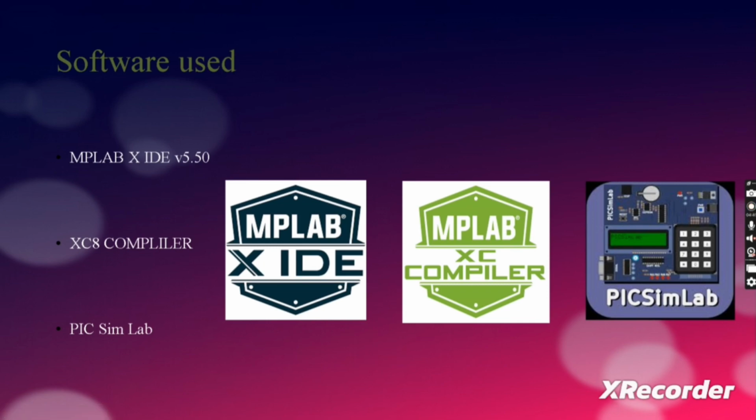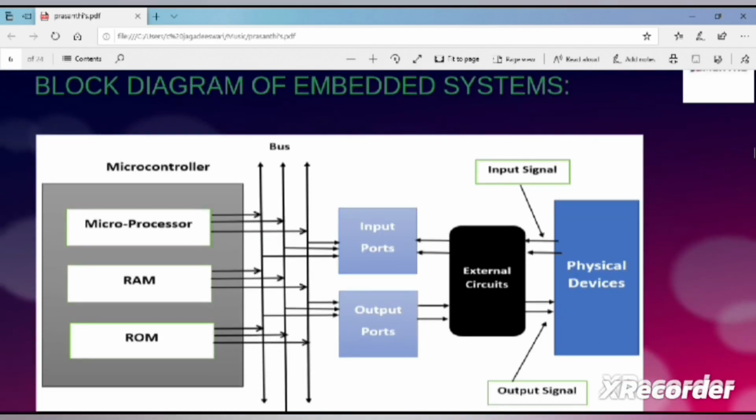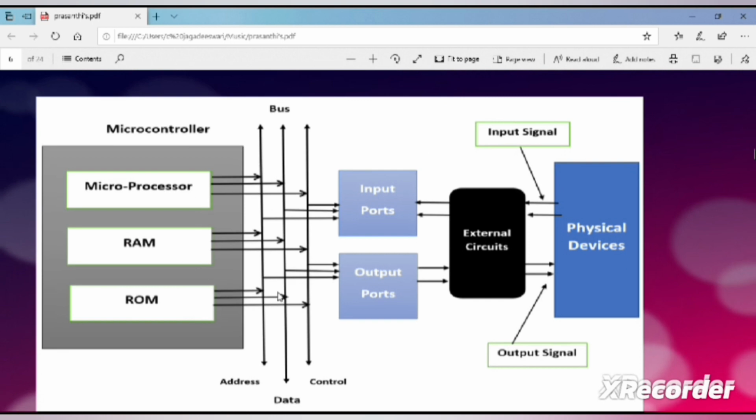These are all the software we are using: MPLAB X IDE version 5.50, and we are using the XC8 compiler to compile the programs, and we are using PicsimLab. This is the block diagram of the embedded system.